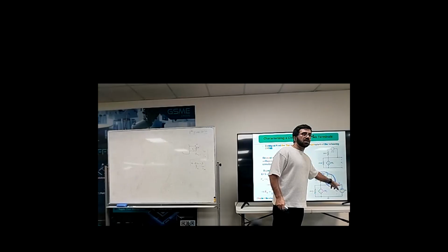easier. If I consider this node as a ground, voltage of this node is how much? VT, yeah. Here is ground, here is VT volt higher. So I can consider here VT. If here is VT, how much is the voltage of this node? 5 volt higher than the negative terminal, which is VT plus 5. I can consider these two nodes as a super node and apply the KVL. That means I should put my hand here.